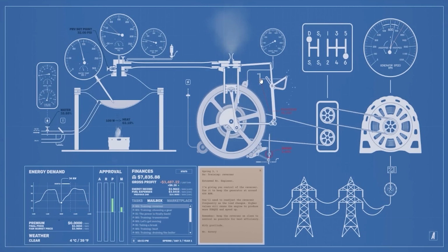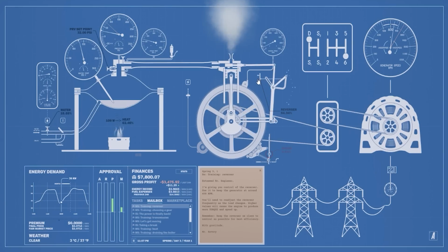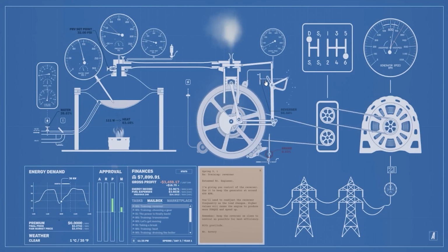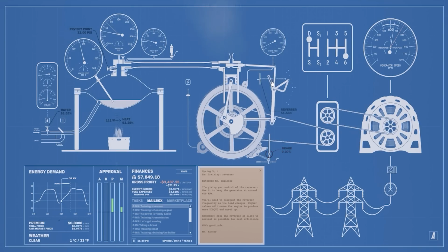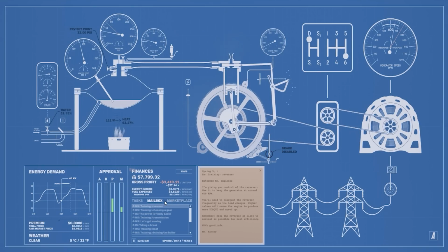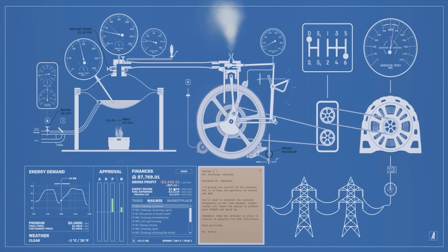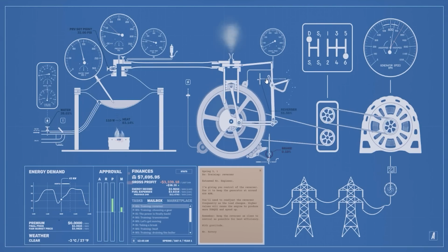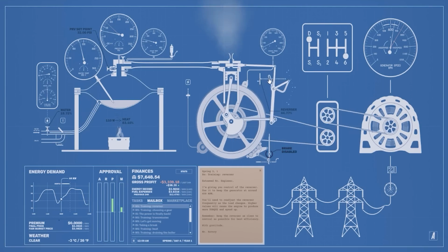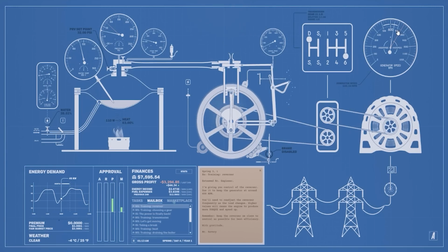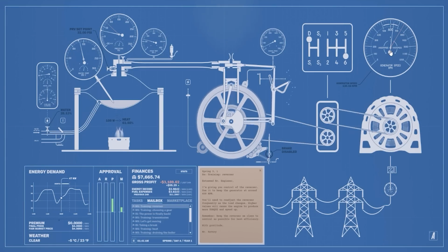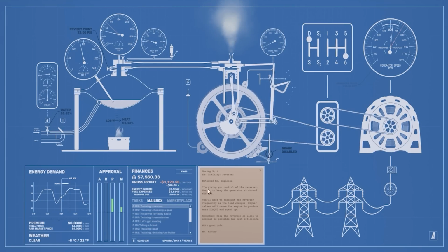Okay, so let's go with close to neutral. Okay. Still sending money back to the... Well, we're sending energy to the grid, so we're getting paid. I'm going to bring that reverser down a bit, because I can see we're getting into overspeed levels. As I said, the rest of it's all being controlled by the AI. That seems about right.